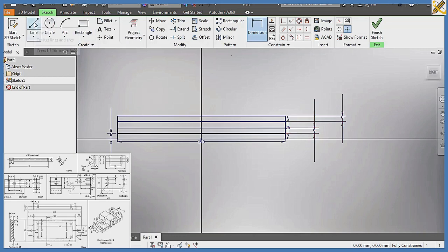I'm going to pick a line in this manner. Standing right here, I'm going to draw this right here. Drawing that line in that area, I'm going to pull another line right there. Draw it right here, then pick my dimension. The dimension of my line from here to here is 6. Enter. Then the dimension from here down here is also 6. Enter.